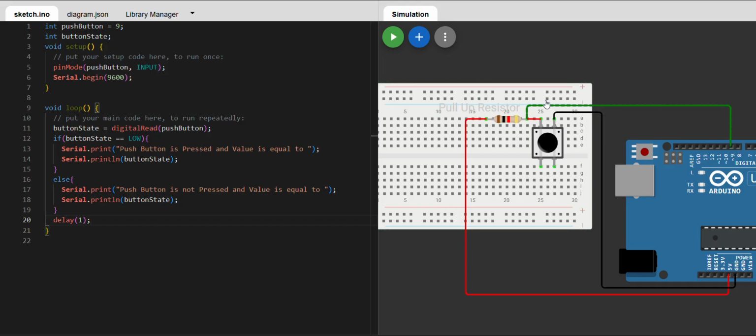Okay, pin 9. What does it mean? It means it's a pull-up resistor. When it is idle or in the off state, the output we are getting from this particular ninth pin is high, right? It means the resistance is pulling up the voltage when it is in the off state. That's why this particular resistance is called a pull-up resistor.